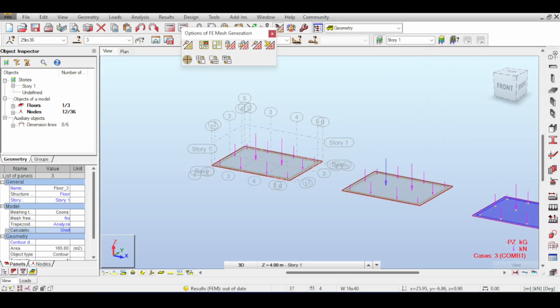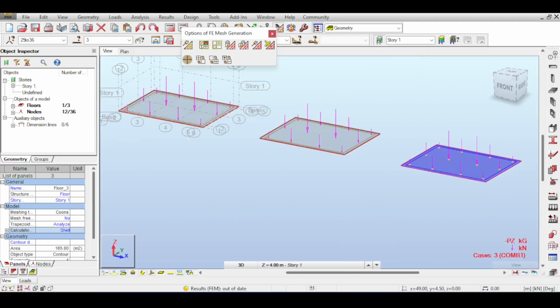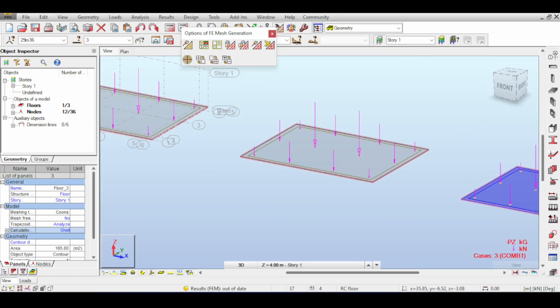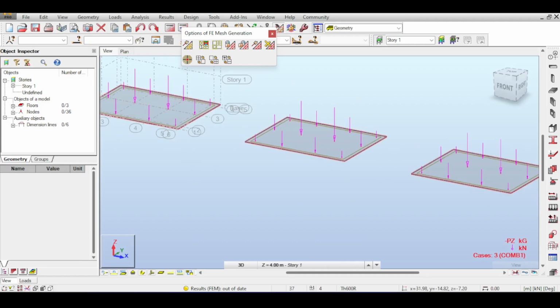While I'm doing this, I want to mention when we use mat foundations. I was taught in the university that, of course, you have spread footings and combined footings and mat foundations. And the idea was that if your footings cover 70% of the ground, then you should switch to a mat foundation. I'm interested in hearing your own thoughts on this. At least this is what our experience has taught us. Anyway, I will talk about this in a moment.